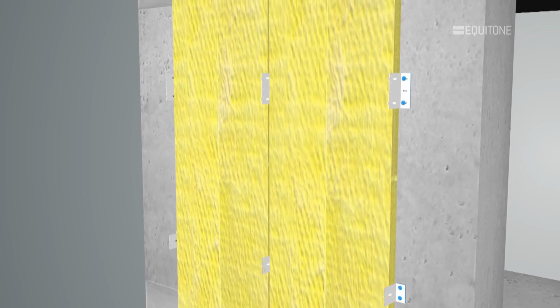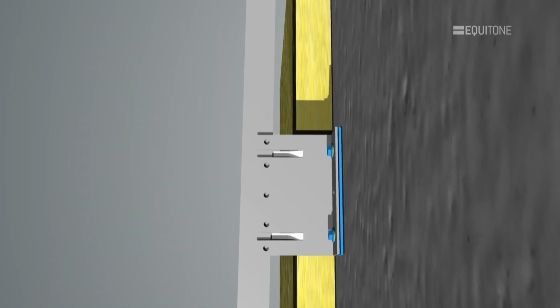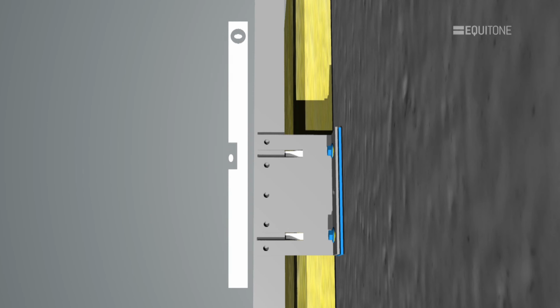Place the insulation against the wall. Using the clip on the wall bracket, insert the vertical T profiles behind the vertical panel joints and the L profiles as the panel's middle support. When final positioning is confirmed, fix the profiles.